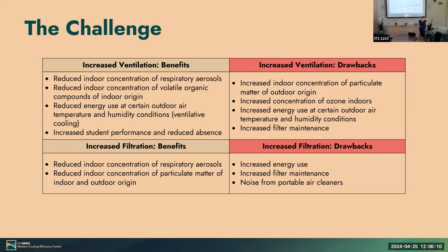And then on the filtration side, filtration has a lot of benefits. When you move air across a filter, you remove respiratory aerosols, and you also remove particulate matter. But the drawback is there's a little bit of energy use with increased filtration and also increased filter maintenance. We can also run portable air cleaners, and those are pretty energy efficient. The main drawback from those can be noise.